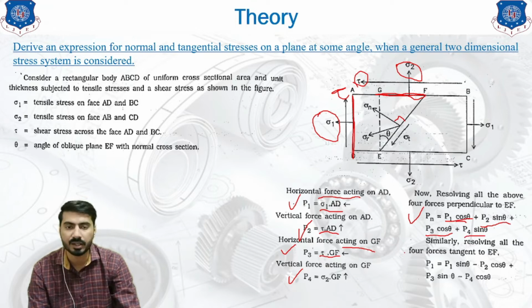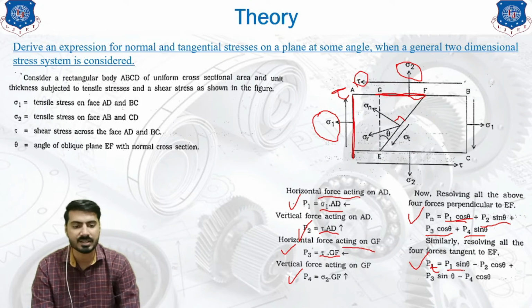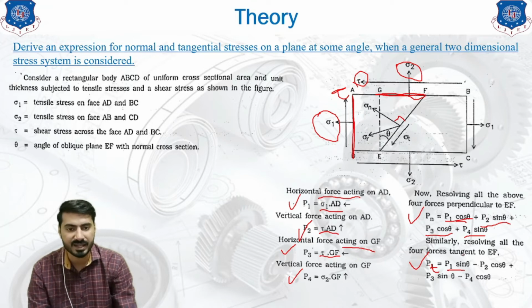If we want to resolve all these forces in the tangential direction, then it will be represented by PT. Let me correct myself. This is PT, T for tangential. So in the tangential direction, we will take it as the opposite. We have taken P1 cos theta in the normal direction, so in this direction we are going to take P1 sin theta. Now, if you remember, P1 sin theta will be in this direction, the tangential direction. So it is going in this manner.